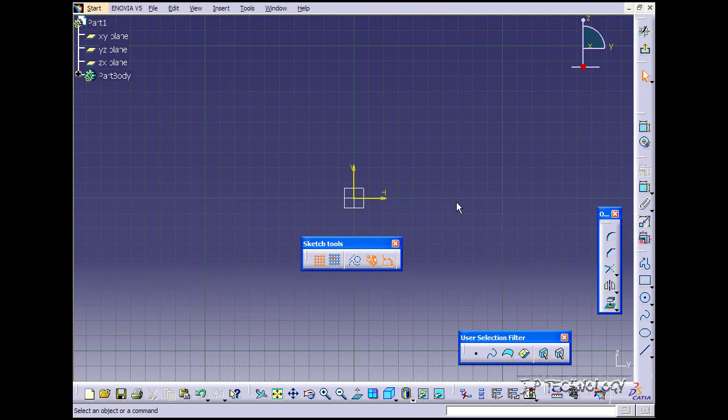I find that snapping to a point is kind of useless. Other people do like it because it gives you a nice full number, but I like to pull out my parts and then dimension everything how I want it to be, and it's never going to snap easily to 5mm increments or 1mm increments for myself. I know that I'm going to have to create dimensions that are not snappable by these means. So in the tutorial, I'm not going to keep the snap to point option on. You're more than welcome to use it, but I'm not going to use it. I'll keep the grid in the background though.